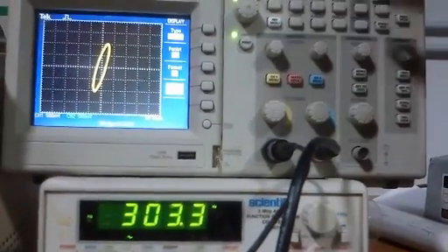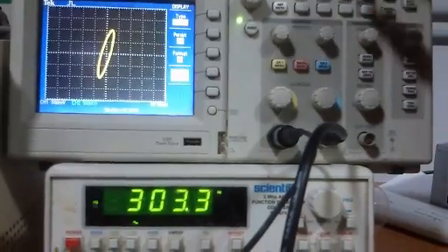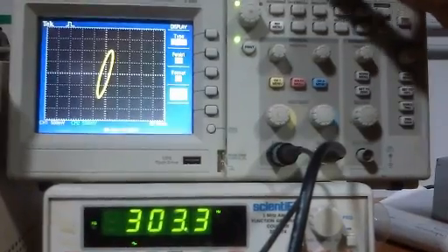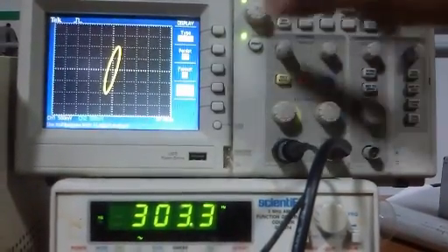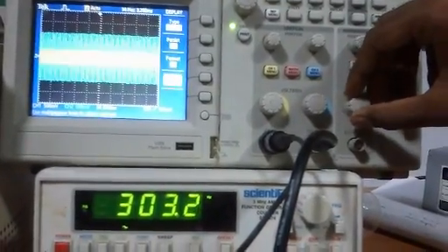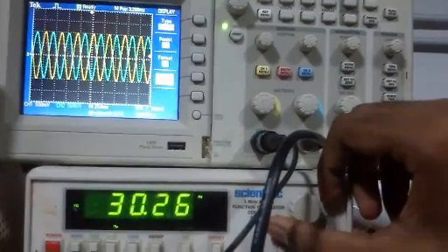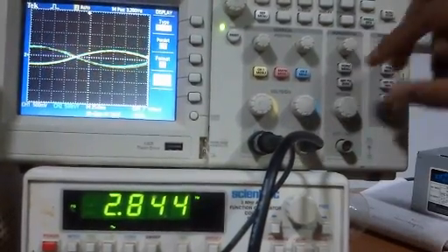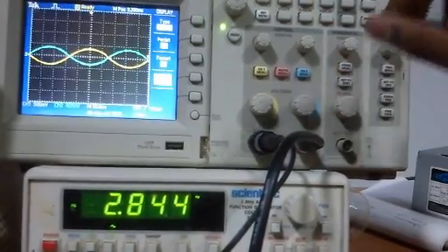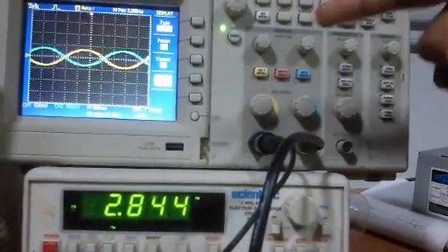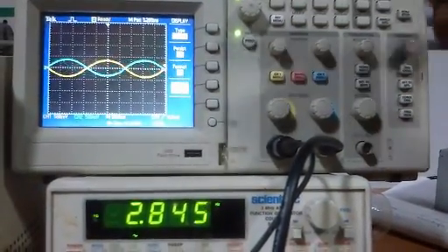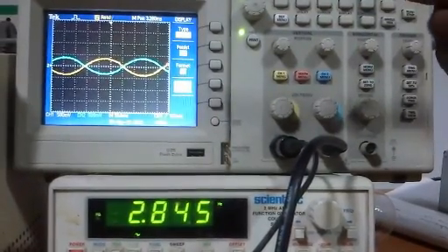So one of the challenges we faced with the cathode ray oscilloscope was we were not able to take measurements for lower frequencies. So this is a digital storage oscilloscope. As you can see, as frequency is reduced, right now the frequency is 2 Hz, and you can still see the signals very clearly. This is not possible in a CRO, and this is one of the main challenges we faced while testing the circuit characteristics. So this is why we shifted to a digital oscilloscope.